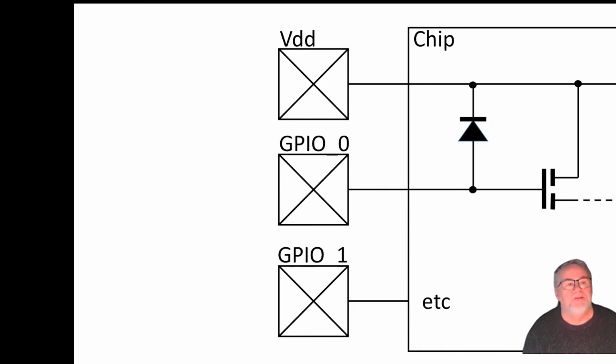So I had a problem I was asked to investigate a number of years ago. This guy had designed something and it was working great at switch on, and then after a few seconds it was stopping. It was a microcontroller, and we couldn't understand what was wrong with it. We traced out the circuitry, and after about 3 days of physically following wires with a pencil to work out what was going on, we found that when he designed the printed circuit board, he had neglected to connect the supply pin of the chip to the supply.